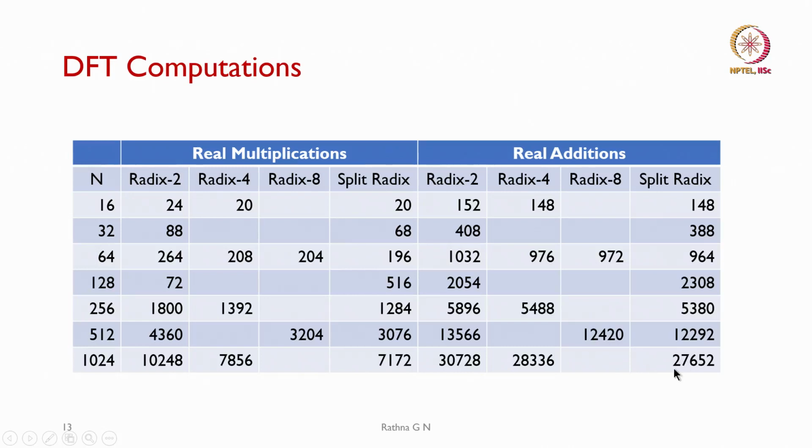So, depending on your application, you choose the radix format. The application may need 1024, 2048 or 4096 points, or if you want to implement much more than that, you can use a different radix format at each stage, combine them and take the output, even if the length is not a power of 2.